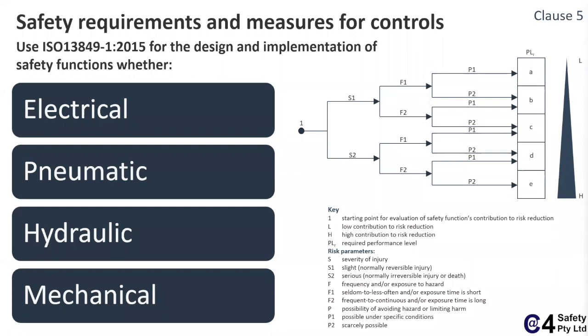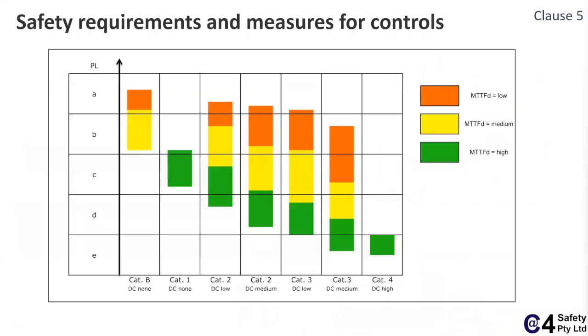So that's something that would have to be reflected in the standard. It does concern me that, having seen quite a bit of woodworking machinery out there in the field, I'm not sure how some of those would come out at performance level C when it is a continuous exposure. Severity of injury is very high, and the possible avoidance of these high velocity ejections is next to nil. Very impossible to avoid. But what does performance level C even mean? Well, let's have a look at this next one, because I think this is probably the bigger worry.